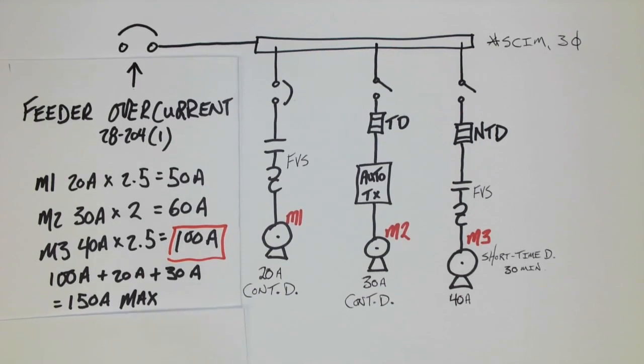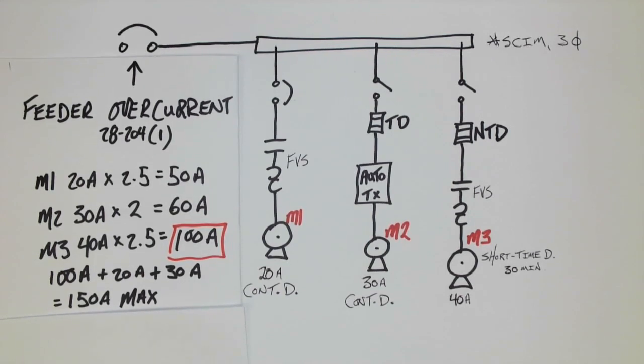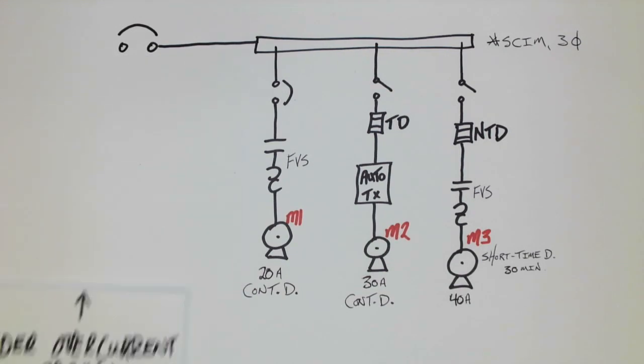At this point, I'm simply going to take my value to table 13, and this is the absolute maximum that I can possibly put in this particular circuit. Table 13 renders exactly a 150 amp overcurrent device. This would be the largest that I would be permitted to place onto this particular arrangement of motors in a bank. So that's how I would establish the motor feeder for this particular motor bank.